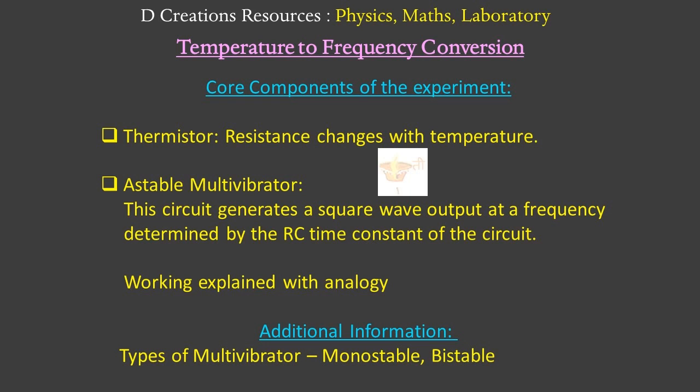And in case of an astable multivibrator, instead of the switches, you actually have electronic components like transistors. So here transistors are acting like tiny electronic switches, turning on and off depending on the signal. And when the transistors will switch is controlled by capacitors. So capacitors are like tiny containers that can store electricity, and they charge up and discharge. And this timing helps control when the transistors are going to switch. And how fast the capacitors charge and discharge is going to be determined by the resistors. So they are going to control that.